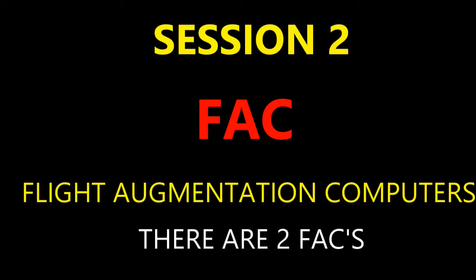Your alpha floor, you have too much angle of attack. That's what we don't want. We do not want that. So it's going to be detecting as soon as there's a sign of those two conditions, which are your threats, then that kind of information can be computed by the FAC or the ELAC, and then that data is sent to the FMGC. Okay, so that combination there is just protecting against that increased angle of attack.